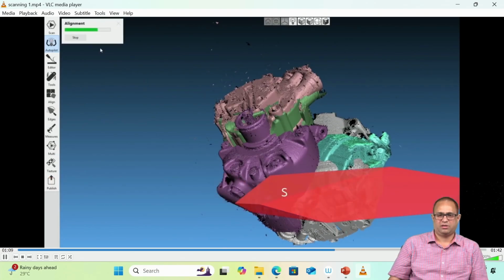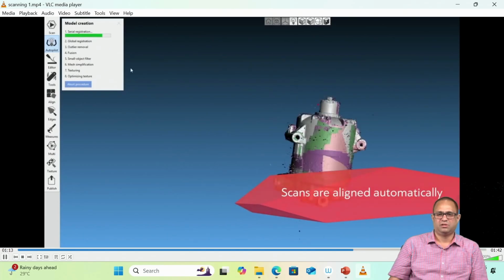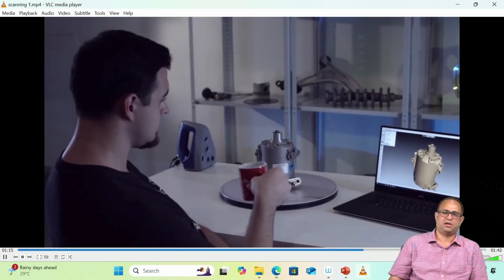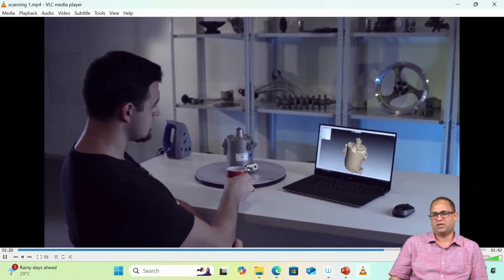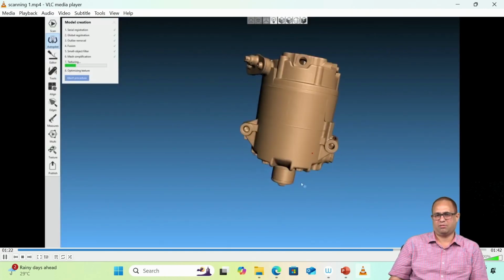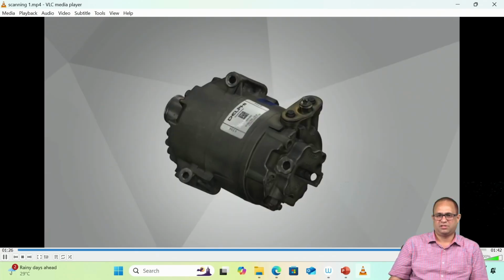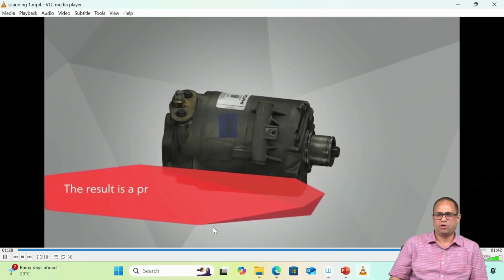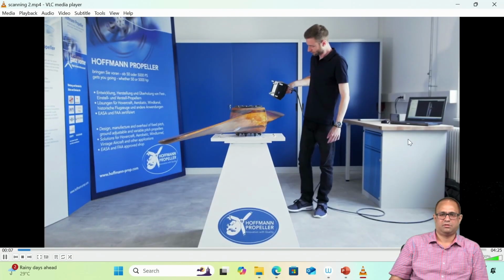In this way the part is processed, and it takes more time than CAD modeling. It is not as simple as a CAD model, and it takes much experience to process all the features. This is how the physical model is replicated as a CAD model using the 3D scanner.